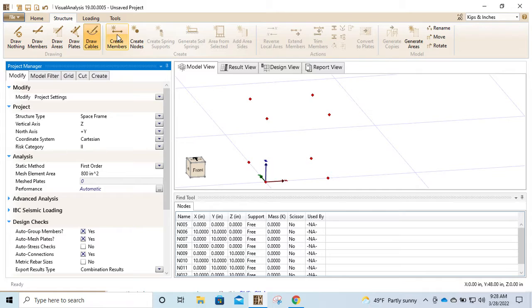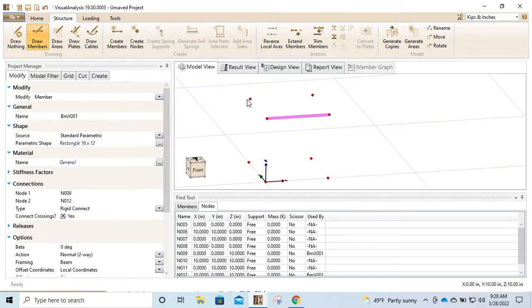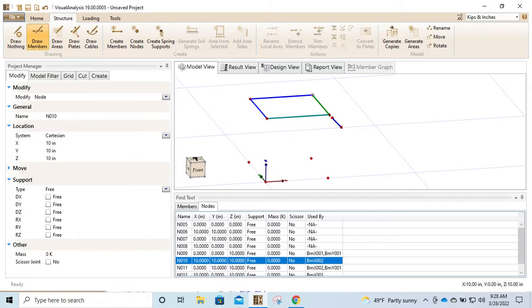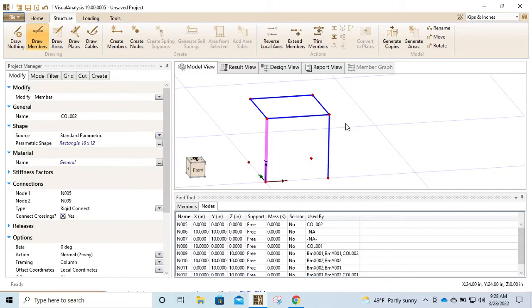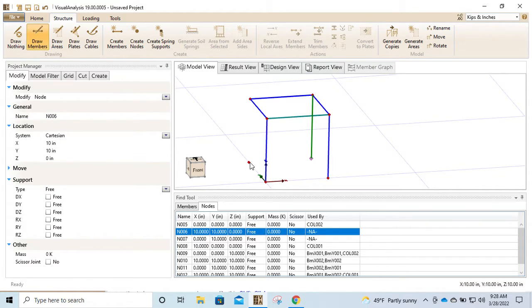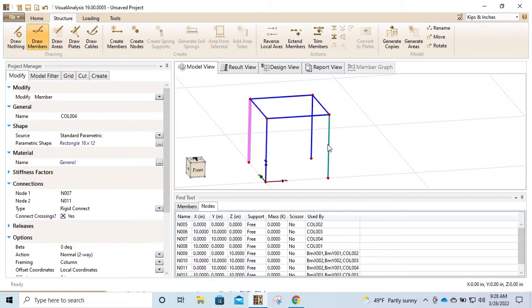if we want to draw beam, create members, draw members. Drew a member. So now we essentially have this pedestal, right? So if we look at these three members, they create a moment frame. We pushed on this table to the side, right? The resistance to pushing is going to be based on the boundary conditions at the bottom, whether it's fixed or pin, and then what type of resistance we have here.